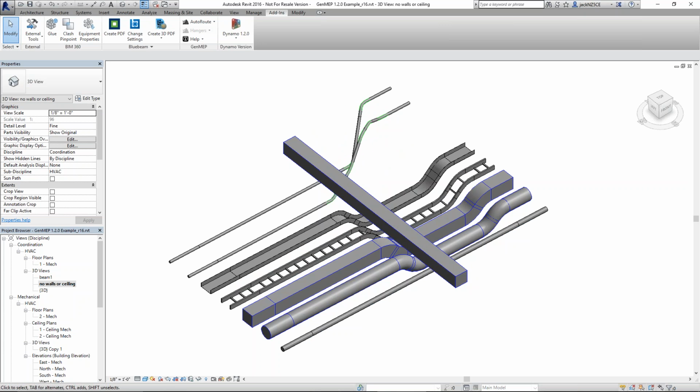Now we have 7 new routes. Because we're storing the element IDs or the GUIDs of these stubs, I was able to move the conduits around as well as change the location of the obstruction and still run the batch file. Model changes can be made by other disciplines and the batch file can be executed repeatedly to generate routes without having to click on the stubs again.